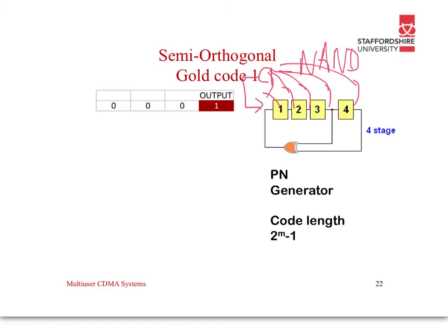What happens is we choose certain outputs of the memory elements to feed back to the beginning. So there's no input here. The output is the feedback stages of whatever we choose. In this case, it's the output of 3 and 4. I could choose any configuration here, and the result would still be the same. So we'll have these as 0, 0, 0, 1, with 2 and 3 as 0 and 4 being 1.